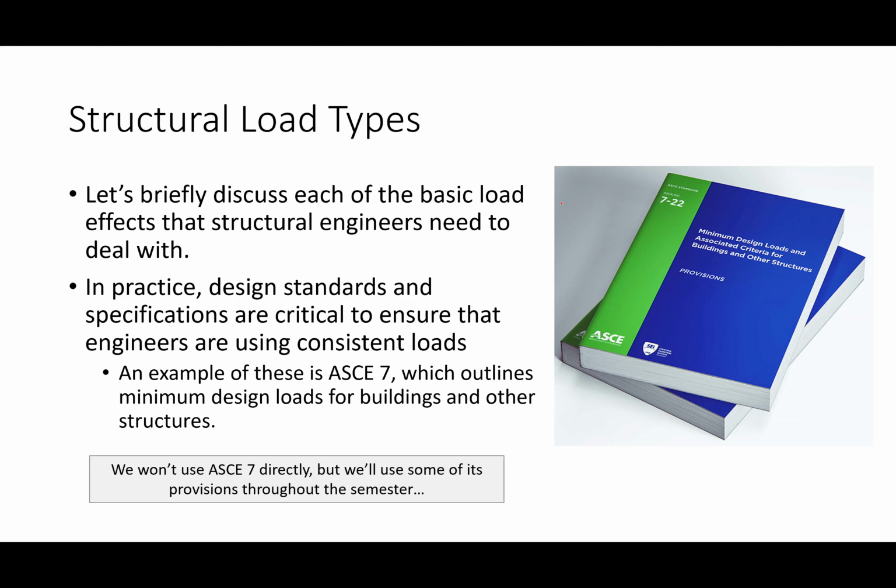That's your gut, right? What I'm saying is that ASCE 7 can establish a baseline that we all go by, okay? And those loads come from actually instrumenting schools and hospitals and churches, etc., to actually see the loads that you should account for. What should the wind speed of a building in Huntington, West Virginia be? What's the number? You know what I mean? That's what ASCE 7 does, it outlines those acceptable minimum load provisions so that we're all doing the same thing. That's what these specifications are intended to do. So it's incredibly important. I'm actually going to show you a hazard tool here in a bit.